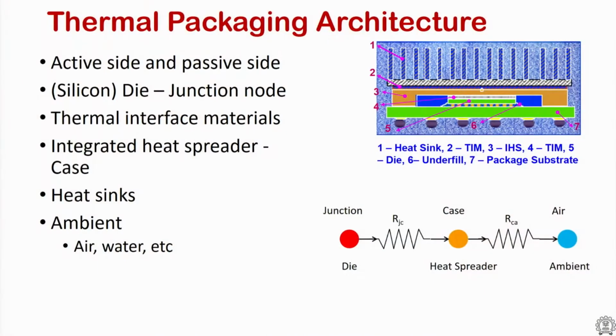If, for example, it is 1 centimeter by 1 centimeter and you make contact with another material of 1 centimeter by 1 centimeter, the area that is actually in contact is only 1% of that. So one puts what is called a thermal interface material to improve the contact area. On top of it, it provides a thermal conduction path between the heat generating source, which is the silicon die in this case, and the integrated heat spreader, which is the copper.